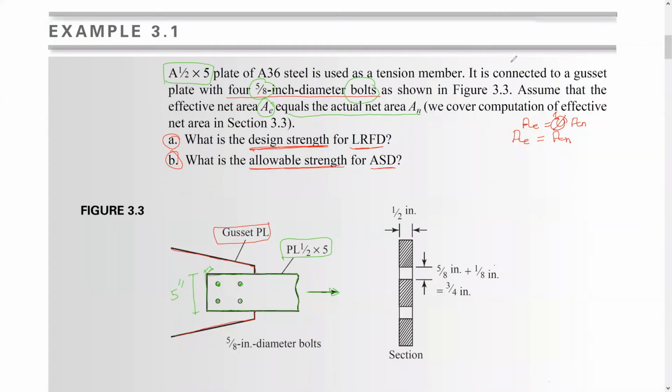Before we go further, if we take a section here, let's call this section AA. For sure, we're going to have 2 holes in this section. Why are we not taking it somewhere else without holes? Because all the time we should design based on the worst scenario.